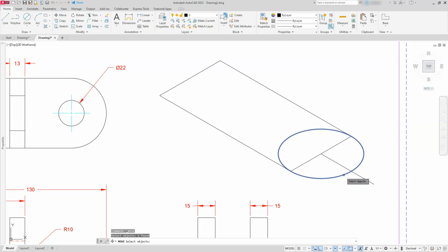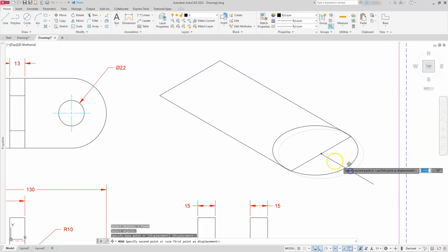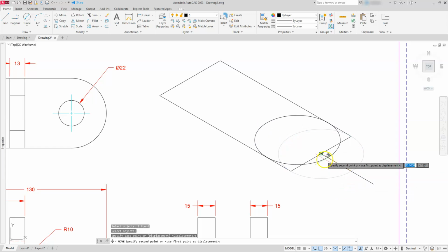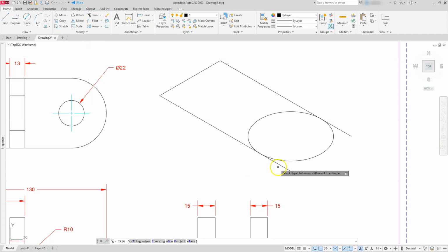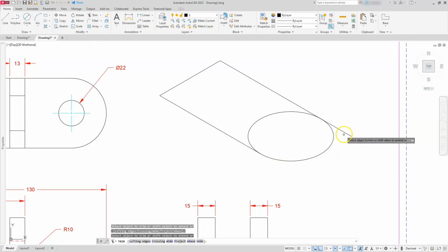Remember that it's an ISO circle. Move it from this intersection to this endpoint. Go ahead and get rid of a couple of lines here. I can delete these two lines, and then I can use the trim command. Remember, I can pre-select with the trim, but since all of these are touching, there's no need to pre-select any cutting edges. So I'm just going to use trim and trim off the parts I don't want.